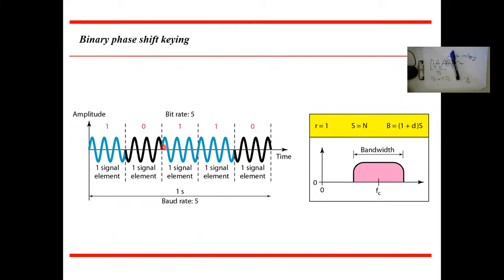However, such a representation will include by default what's called the phase overlapping problem again. So you increase the noise immunity, however, you also increase the bandwidth. Again, remember, we never have a free lunch. Whenever we add one point, you should lose something to compensate. So this is a representation of ones and zeros in binary phase shift keying.